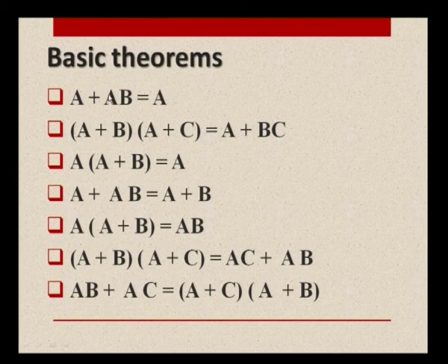Here what we can do is, because of the associative property, A could be taken common. Once A is taken common, it will become A within bracket 1 plus B. 1 plus B is 1 itself. Again A dot 1 is A itself. So, this is how we can explain each expression, but the results are very important. So, I would like to just show the results as theorems. Wherever we come across these forms, directly the results could be used.